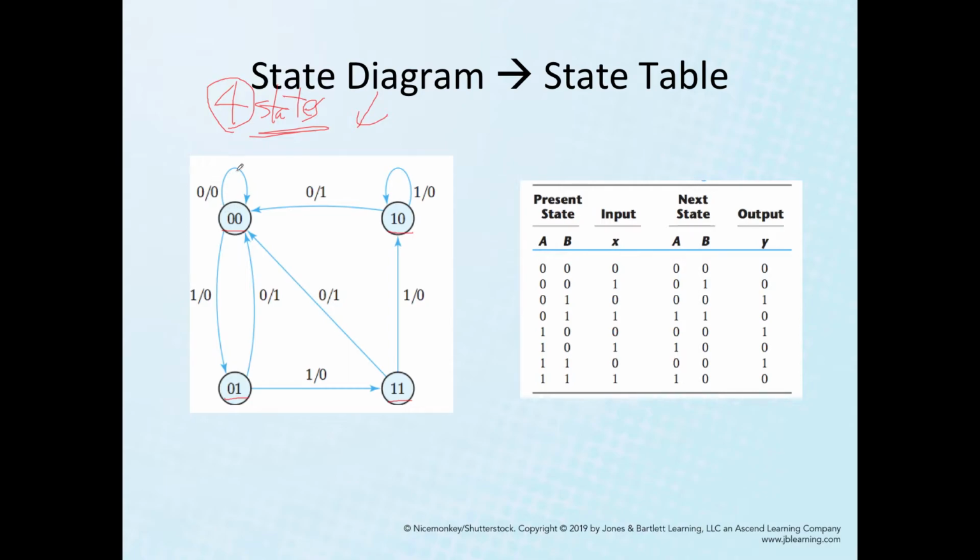And then an arrow represents a state transition, and each arrow has a label of the form some number slash some number. The first one is the input, and after the slash the output is specified. In this system, we assume that there is only one input. How do we know it's one input? The left-hand side of the slash is only a single digit. We are talking about binary systems, so a one-digit input means one input only. So the input is 0 or 1.